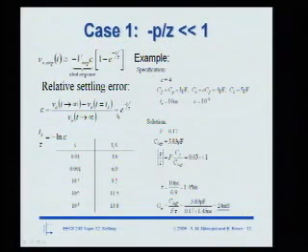And so to achieve a certain resolution, I have to wait log of the resolution time, right? If I solve this equation, T is minus TS, the settling time, this should be TS, is minus tau times log of epsilon, right? And that's actually very fortunate, because the log function grows very slowly. So if you need more and more resolution, you only have to wait a few more time constants.